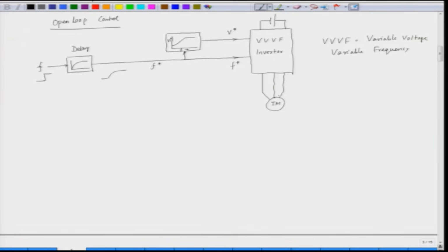Now, if we draw the torque speed characteristic of this drive, we get the following nature. Our speed is on the y axis and torque is on the x axis, we have the origin here. So, this is the characteristic that we get, for the motoring and for the regenerative braking.